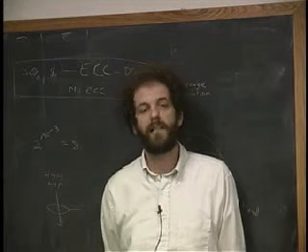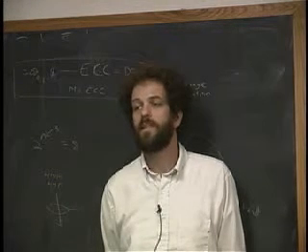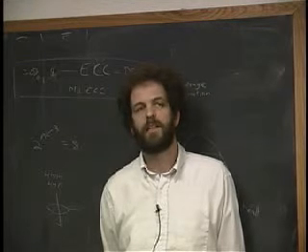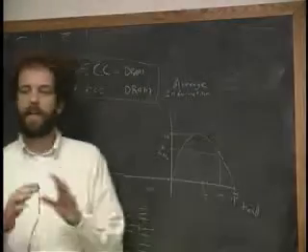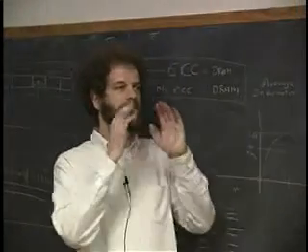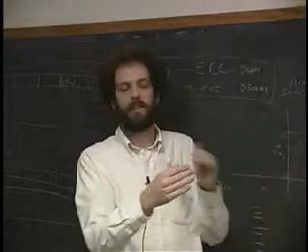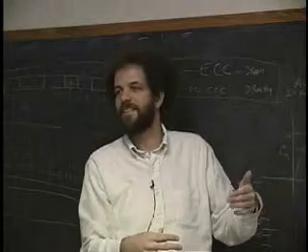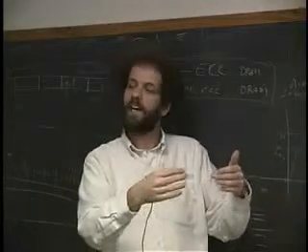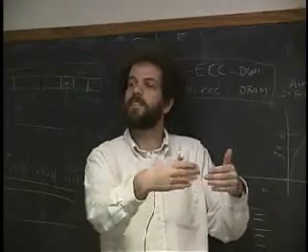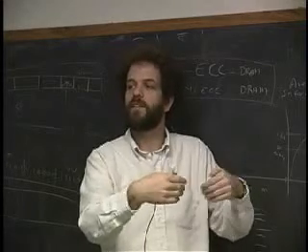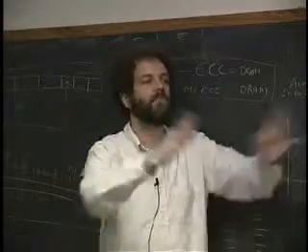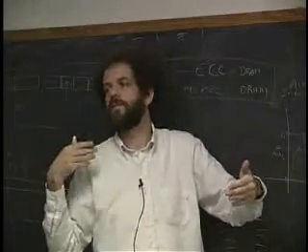If we either do not connect the wire at the end, or if we connect it to ground, we get a reflection. Okay? And it's hard to believe this, but if you're in a canyon, and you yell down the long way of the canyon, and at the end the canyon opens up into nothing, and let's say there's a ceiling to the canyon. Okay, lots of ifs here. You'll actually get an echo off of the discontinuity at the end of the canyon where the canyon opens to the wide, wide world. As suddenly this traveling wave is going pop, a negative wave will come back.